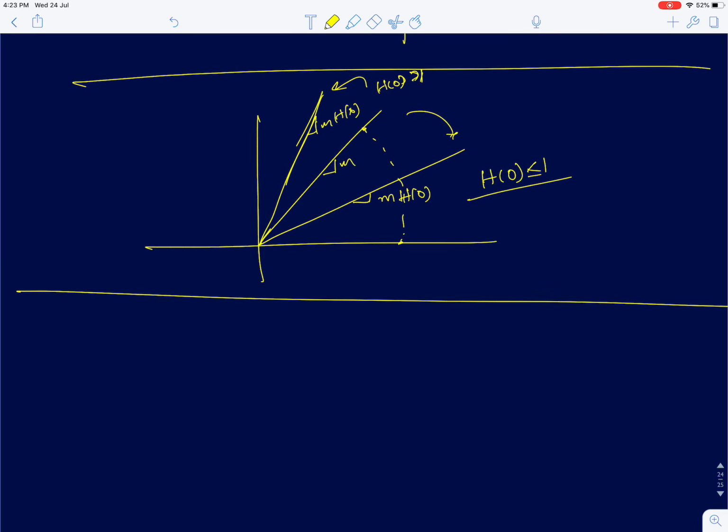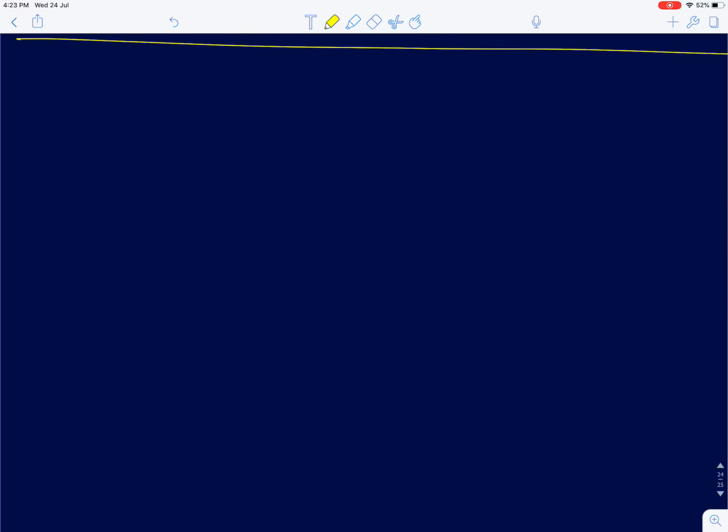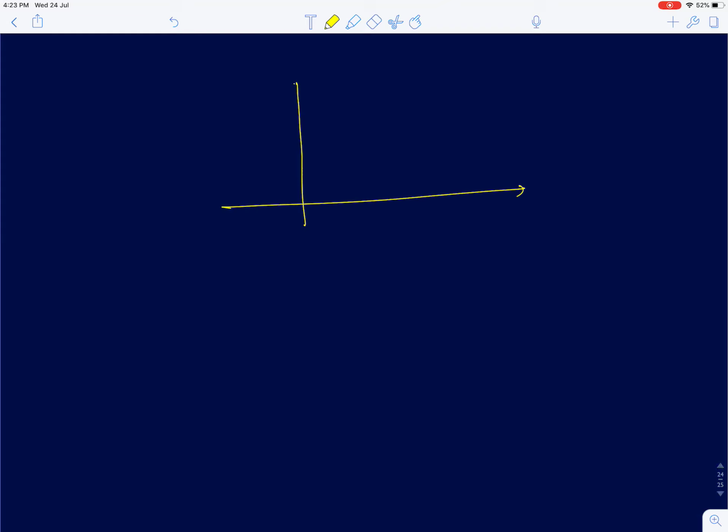So that's about a first order system. We already discussed a ramp input to a first order system, a simple single pole response. What we said was that the input is increasing linearly, and the output in the steady state looks like the input, with input and output delayed by tau seconds.